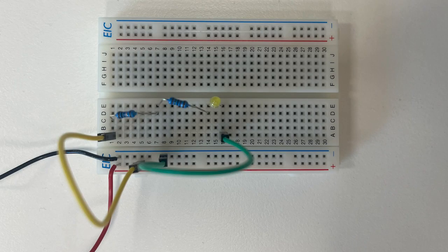So what I need you to do there first, when you're putting the LED into the board, have a look at the way it's positioned on the overhead and make sure it's positioned the same way. If you position it across the row, it's going to connect the legs together. So you want to position it the other way around so it's not shorted.